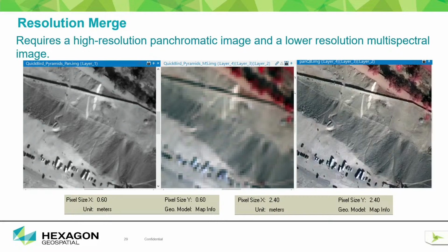Now we can see that this data has no color value here, but here you can see that the merged product has radiometric and spectral information, both are there. So in this way we can improve the imagery for data analysis. That is known as pan sharpening and resolution merge. The two resolutions, we have merged them.